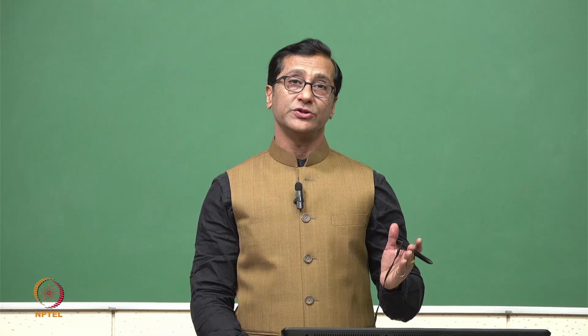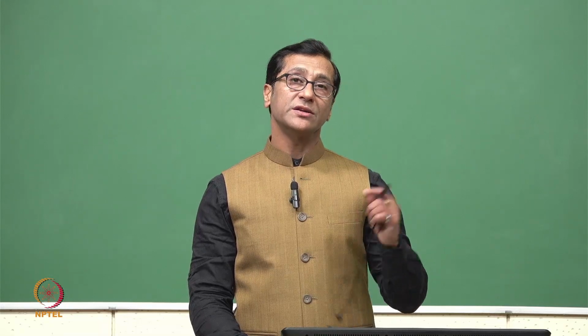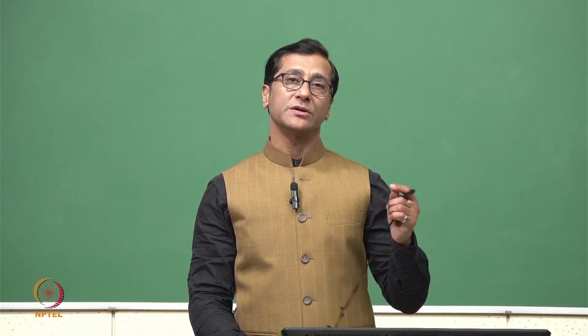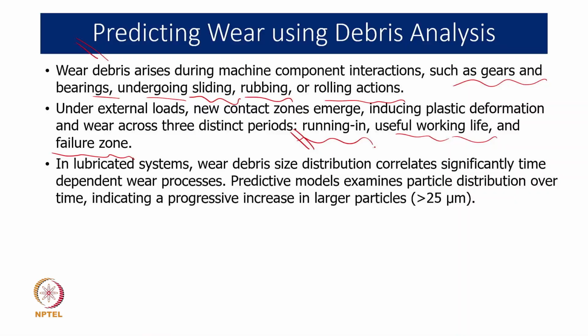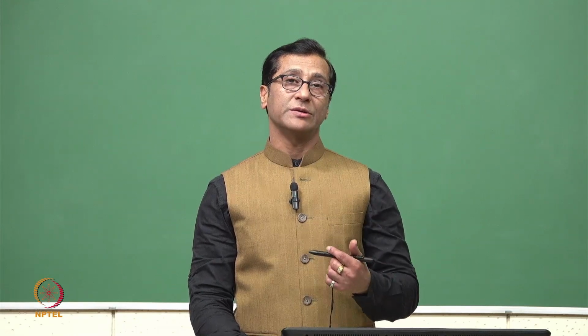Initially I'm applying a 100 Newton load, and running-in may be over after say 200 hours. But if I increase the load by a delta, maybe even 20%, quite possibly the running-in will start again. It is not going to stay at the initial level only. So we need to really think about whether we are able to predict these kinds of things appropriately.